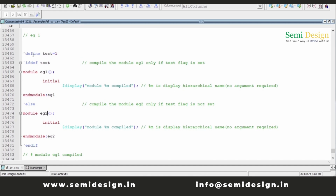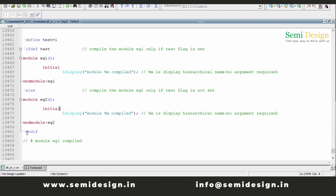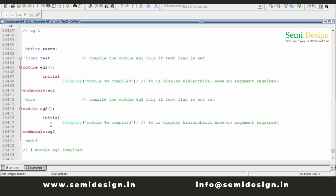So this is backtick define test equal to 1, then backtick ifdef test. It means compile the module example1 only if the test flag is set. Else, backtick else, compile the module example2. And I am ending with backtick endif. So we will see how it compiles example1 and example2. Since backtick define test is equal to 1, it will compile example1. Now we will run this code.